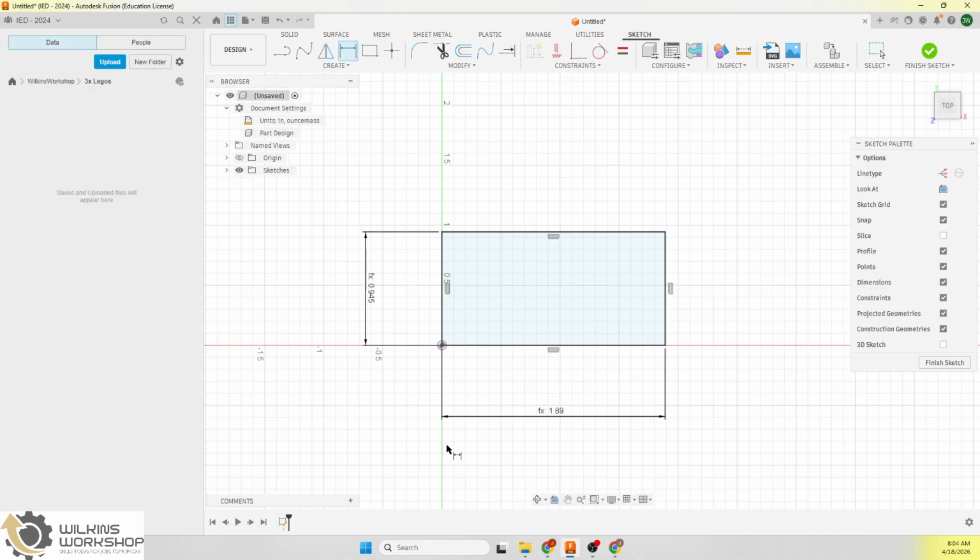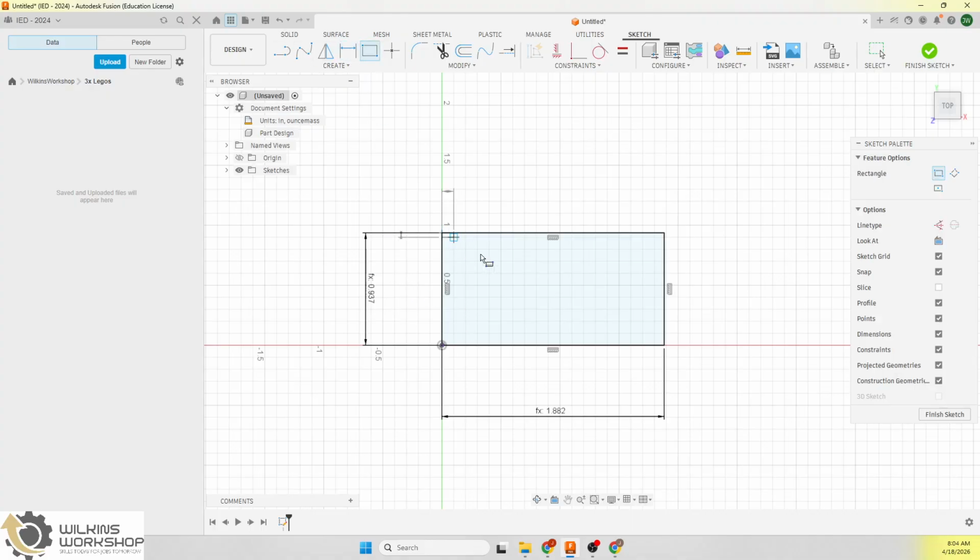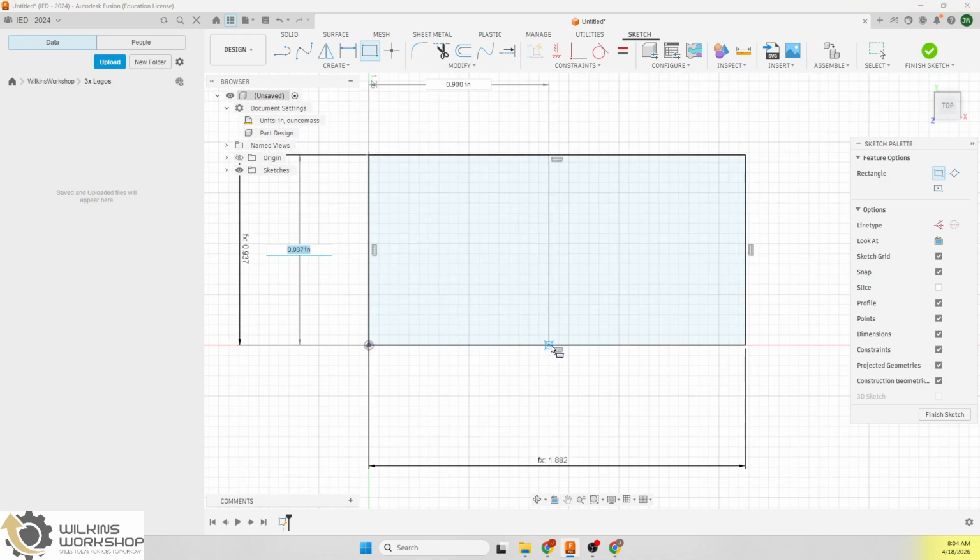And that is the size of our Lego, but remember, we're going to remove material from the outside of both of these. So I'm going to go back and edit, and I'm going to say that it's minus 2 times kerf, because on the outside we're removing material, a kerf on each side. And I'm going to do the same thing here, minus 2 times kerf. And you'll notice that this side is not twice the length of this side, which is what you find out with Lego, the reason is because you have a 1x1 that sits about here, and then you have another 1x1 that sits here.